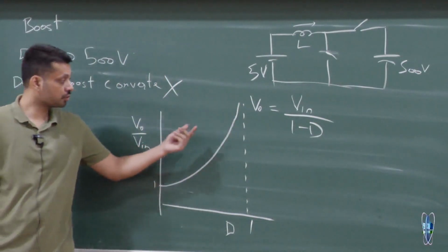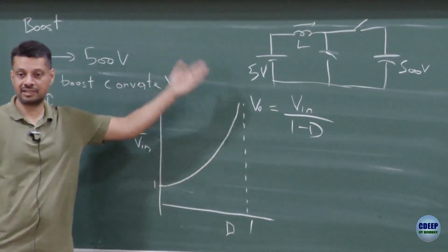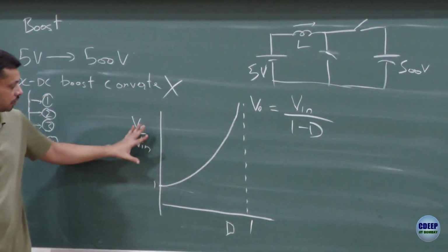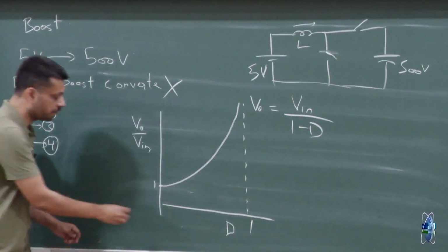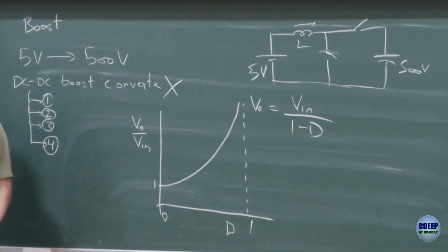That also shows us that a small deviation in D could change the output voltage substantially, right? And that's problem number 1 with the microcontroller precision. But this is how the output gain versus duty cycle would look, D going from 0 to 1 for an ideal equation.